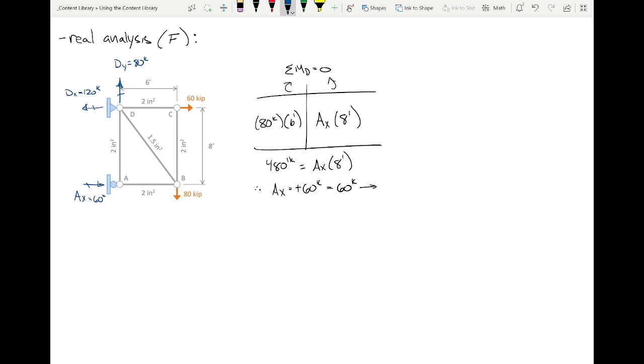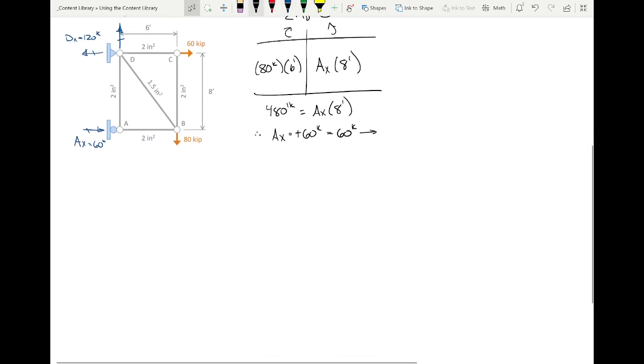All right, okay, so help me out with something. We need to solve the entire truss, right? So we need to use method of joints or method of sections? Probably joints, right? So what I'm going to do is blow up this entire truss and try to do the method of joints analysis all at once. So let me scroll down a little bit. Now, by the way, does anybody know what the slope ratio of that diagonal is? 3 to 4, right? That's 4, and that's 3. Okay.